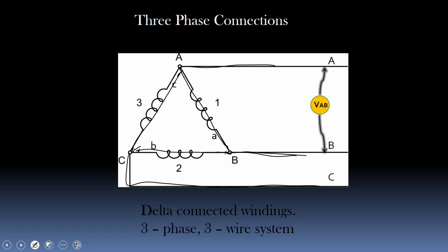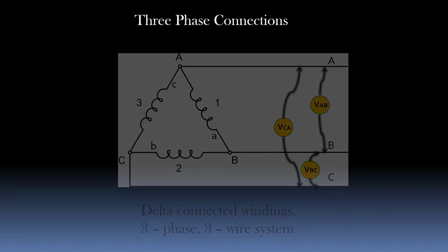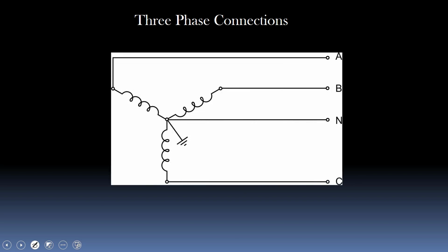So on this delta connection, we are going to get 3 different voltages. We're going to get voltage A to B, B to C, and voltage C back to A. These are called line voltages, and in this case, it is the same as the phase voltage. We have a whole module coming up on delta, and we are going to study this quite thoroughly: how these voltages come about, connecting loads to this, etc. So quite a bit coming up on that, figuring out current flow as well.